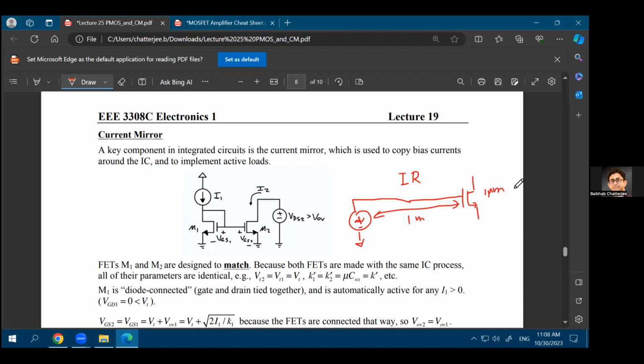So you can just imagine the scale at which the voltages go through, for example, from here to this point. Now at every point, there will be some amount of leakage. Let's say you have a resistor to ground over here, and that would mean a small amount of current flows through this resistance. This could be some amount of leakage resistance as well. Even the gate of the transistor has some kind of leakage resistance. That means there would be a current flow, even though we say that there is no current going into the gate of the transistor. There would be some current going into these leakage paths, which are present all throughout the wire that you connect with the gate of the transistor. So there would be a current flow over here, over here, and through this resistor as well.